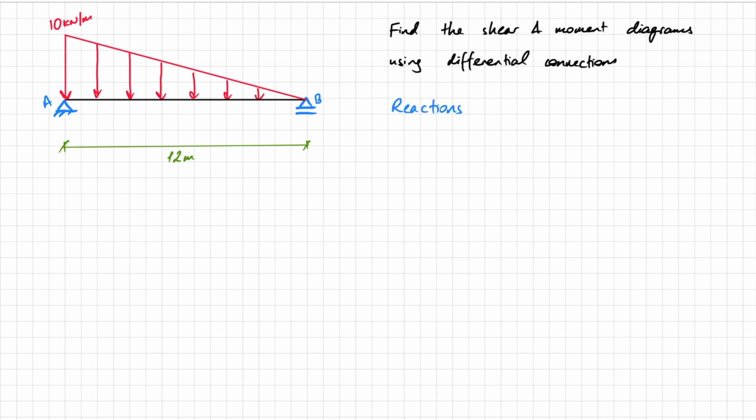And we'll do that just by using the three equations of equilibrium because this is a 2D problem. So I'm going to put here quickly the directions of the reactions. Remember, with no directions, any numbers and signs that you get are meaningless. So starting off with these directions, the sum of forces in x has to equal 0. So we can see that we've got Ax plus nothing else in the horizontal direction, so that equals 0.